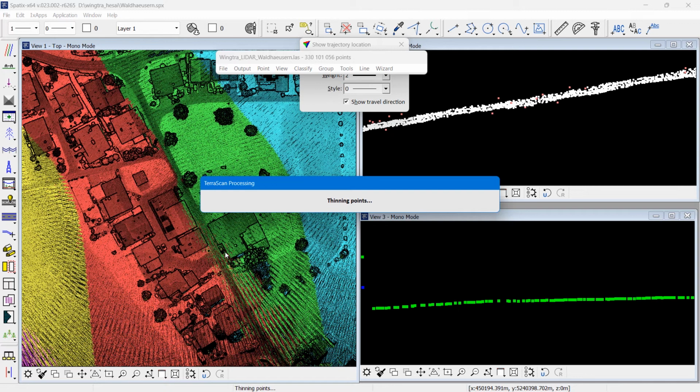So in the beginning we had 158 points per square meter. Cutting overlap removed about 1/3. So we have now about 100 points per square meter. And we don't need every point to decide what is ground, what is tree, what is building roof.